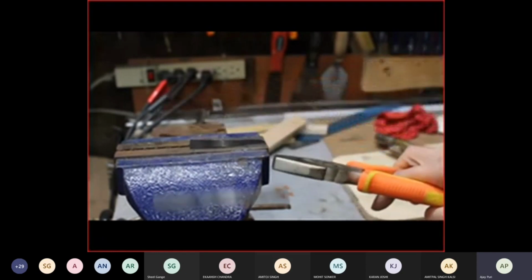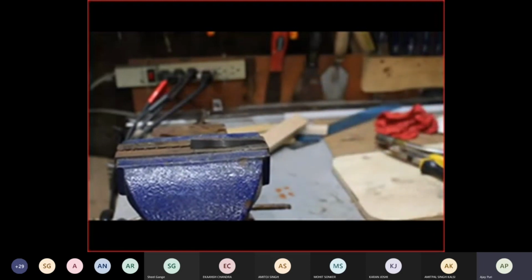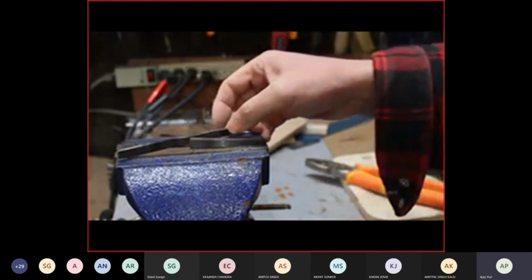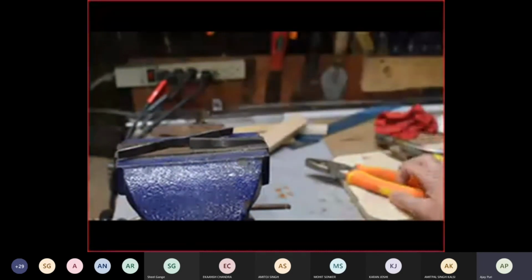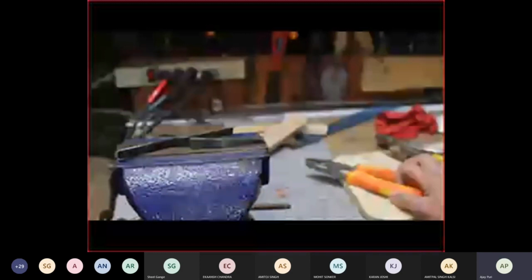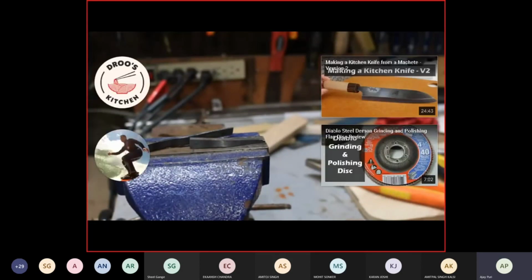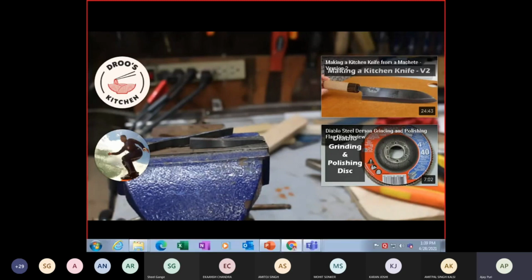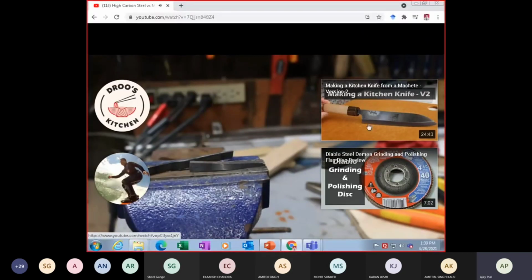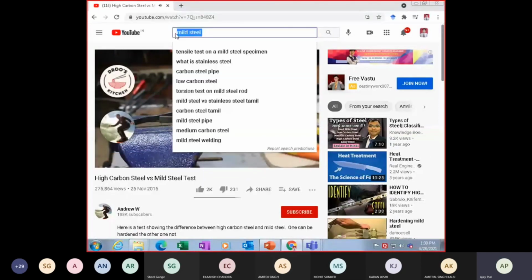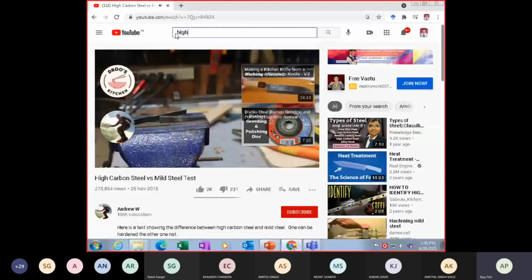Typically nuts that I'm using to make rings out of are made out of mild steel. So if I heat it and then quench it, all I'm doing is speeding up the process of cooling it down. I am not hardening it whatsoever. This can be applied to any type of steel, particularly since steel has iron in it, meaning it's ferrous, as opposed to non-ferrous metals that you also cannot harden by quenching. You can work harden some of them, but you can't heat them up and then quench them and expect them to harden.